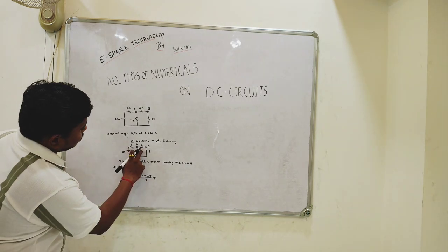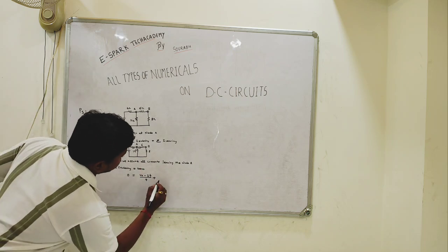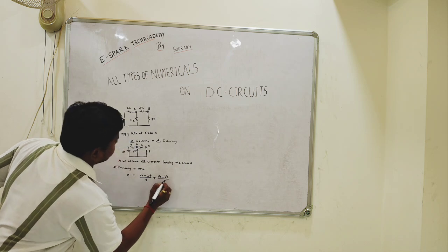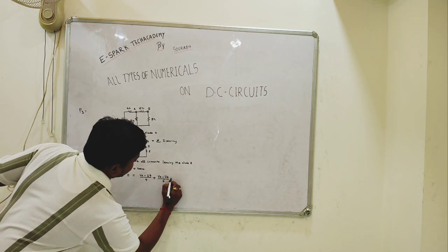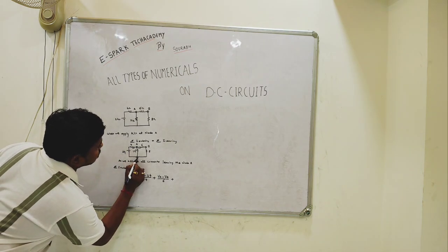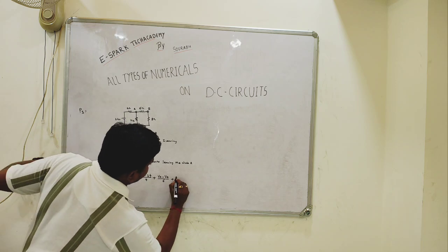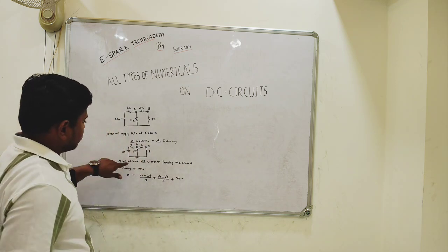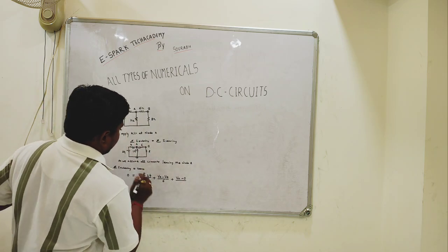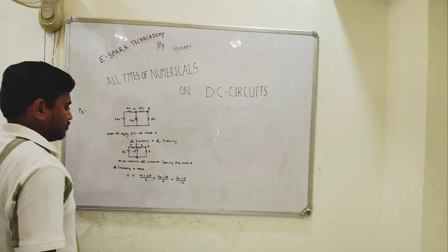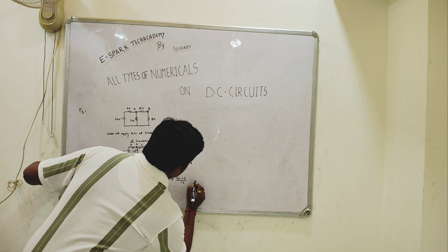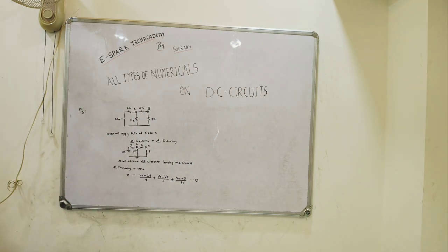Now if you look after 6 ohm resistor, we will get as VA minus VB divided by 6 plus, now as this is connected to ground, VA minus this 0 potential divided by 12. This is the equation which we have to solve for node A.